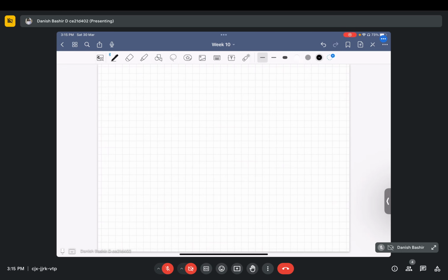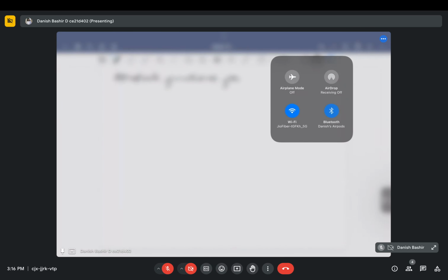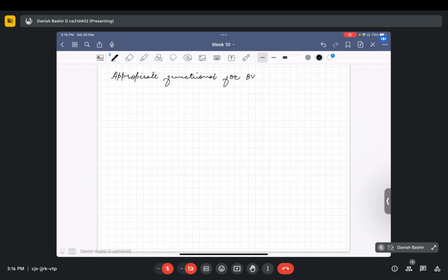So the appropriate functional for the boundary value problem, BVP, we can write as I of T equal to the integral from x naught to xL of k by 2, that is k of x, dT by dx whole square, minus p by 2, that is p of x, T square, minus qT, dx.